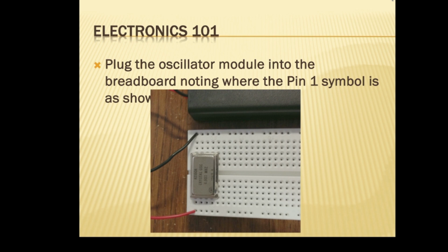This network is what we're calling a filter. So how is this used to modulate voice or like how? I guess this is the beginning of a radio, right? It could be. The frequency generating elements for it, yes. We'd come out with a digital circuit, which is going to give a square wave, but you need a rounded wave to feed the rest of the circuit. So you put it through a filter, round it out, and let it go on through the rest of the circuit. That's the idea behind it, yeah.